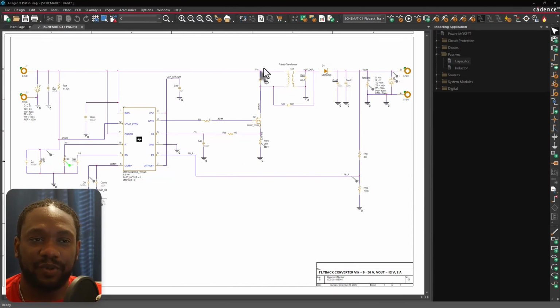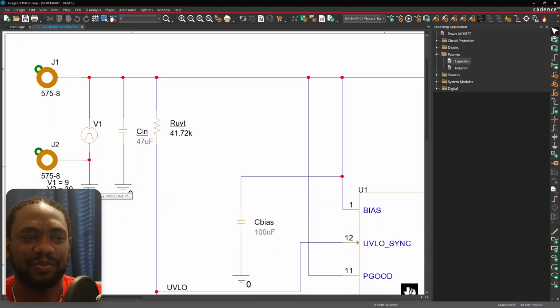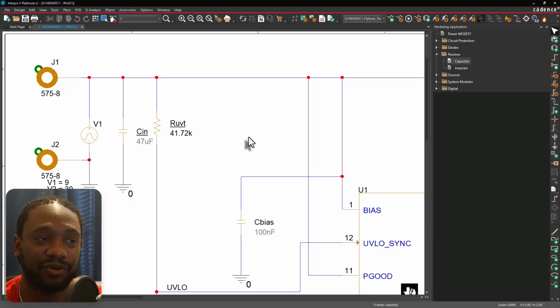So the first way I optimize for circuit simulation in PSpice is to use non-ideal models for devices. Let me give you an example. Here, this power supply, right? Instead of using a pulse, I use a ramped voltage supply on the input voltage, because that mimics reality. It also helps the solver solve things more easily.